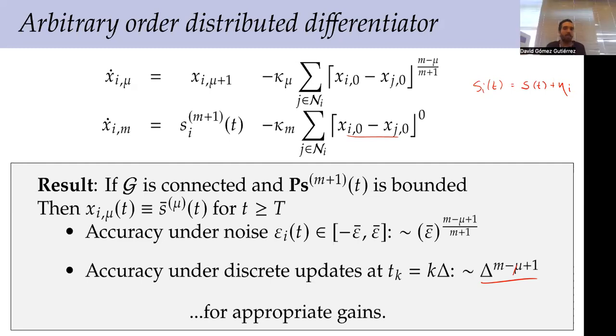But if you have a centralized differentiator, you will get some numerical chattering with some discretization and sampling rate. And if you differentiate that signal distributedly with this algorithm, is the chattering level improved or worse? I think it will be worse.